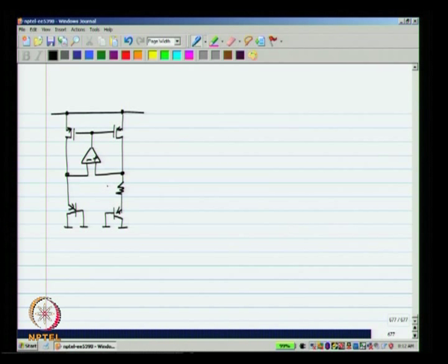In this, VB1 is available in these two places and this is VB2, and to add PTAT voltage to this, we recognize that the currents in these two branches are proportional to absolute temperature and add a resistance in series.